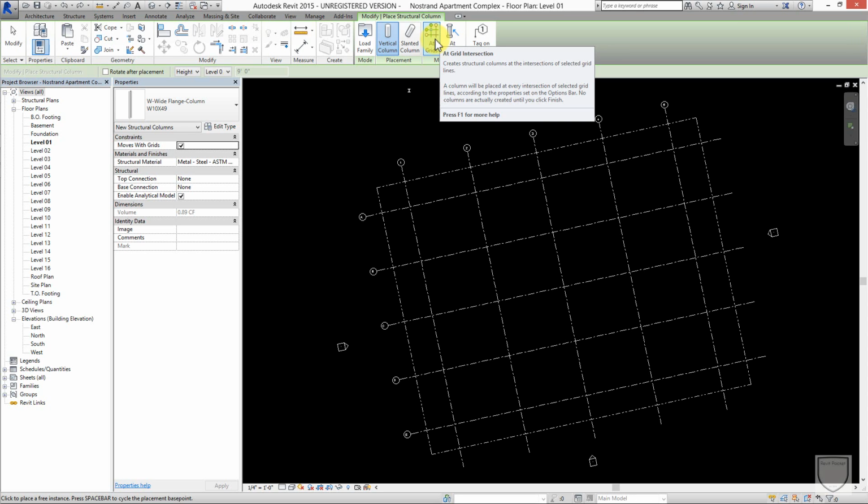As an architect, we're usually interested in getting the structural information. In the Revit world, we'll get it from a structural engineer, and then we'll put a column enclosure. So that's where you may actually use the architectural column. What I like to do is use the structural columns that I get from the structural engineers and modify them slightly so they appear to be architectural. It's a little trick that I use to keep things moving as there's coordination efforts going on between the architect and the structural engineer.